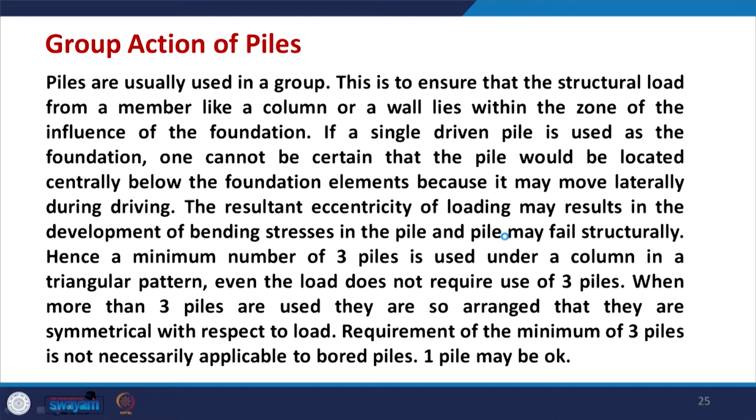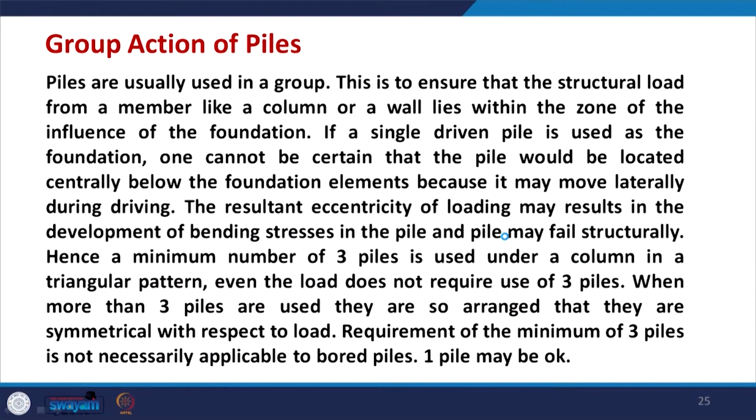This is important. Let us say I have a single column and below the column I have a pile. Initially we have made sure that the center axis of the column and the axis of the pile coincide, but when we install the pile, it may move a little bit, and there could be some eccentricity, or there could be an inclination, and then if you are using a single pile, it could be not safe. The resultant eccentricity of the loading may result in the development of bending stresses in the pile, and the pile may fail structurally.